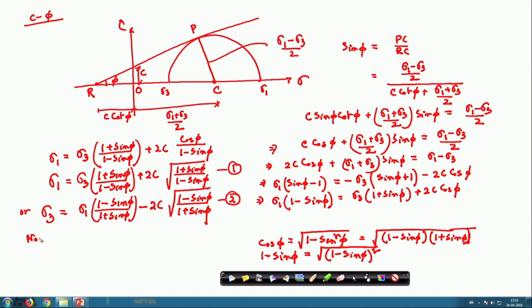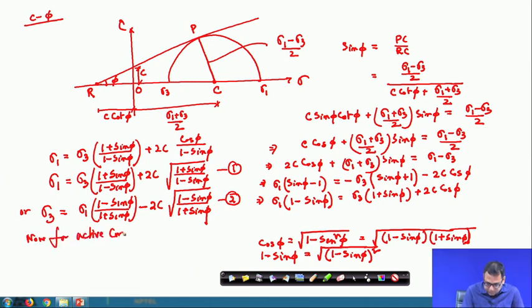Now, for the active case, your sigma 3 is equal to P A and sigma 1 is equal to gamma z. Because this expression I am deriving is not for an inclined surface, it is for a perfectly horizontal surface, where the inclination is equal to 0.